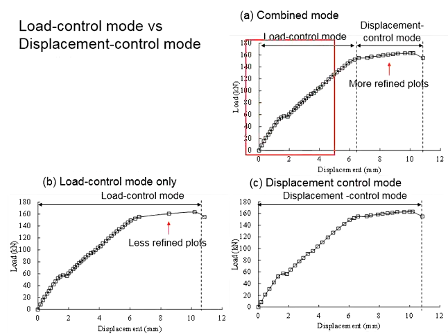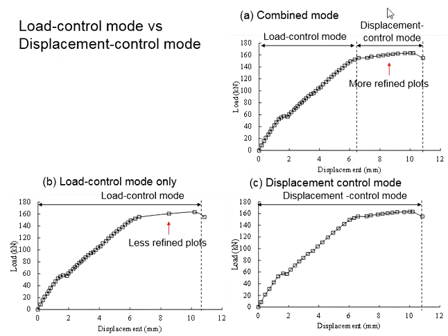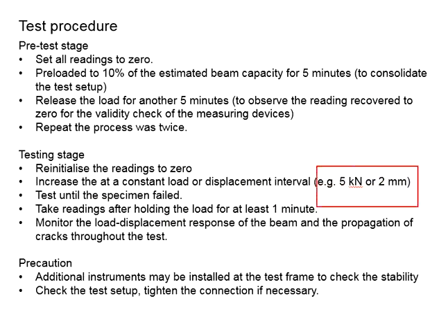Now this comes to your wisdom in determining the intervals. If you find the plots are too closely spaced, you can enlarge the intervals here. If you feel the plots are too far away, you can reduce the interval. That's why you need to monitor the load displacement response of the specimen in real time, as once the testing has started, you cannot redo the testing.